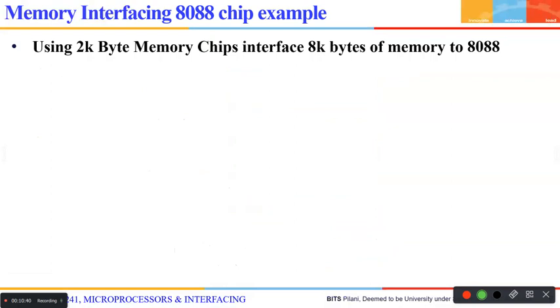Okay. So it's not underutilized. The 8086 microprocessor can take 16-bit data from the memory by using 2 memory chips in one machine cycle. The lower byte it will take from the given address, the higher byte it will take from the odd address. We'll see that. It's very interesting. Just try to follow me. Come to every class. If you have not understood, ask questions.